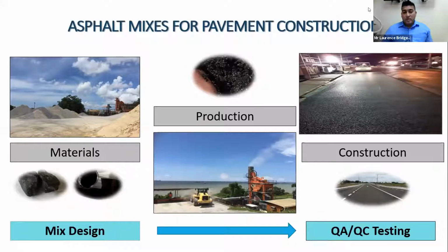Combinations of the aggregate materials and suitable binders are used to develop optimum combinations to be input into the manufacturing process. When we consider the manufacturing process, controls are required starting with the stockpiling of the materials, including ensuring that the materials used for manufacture match those analyzed during the mix design process.